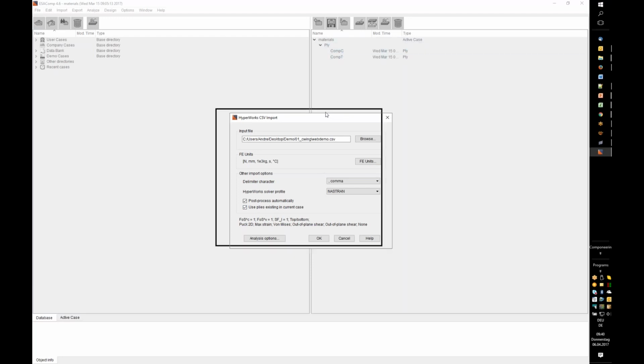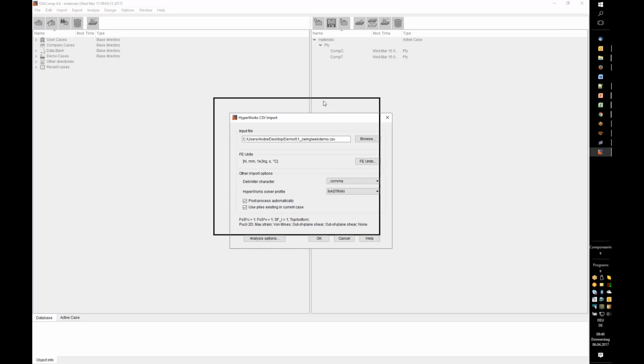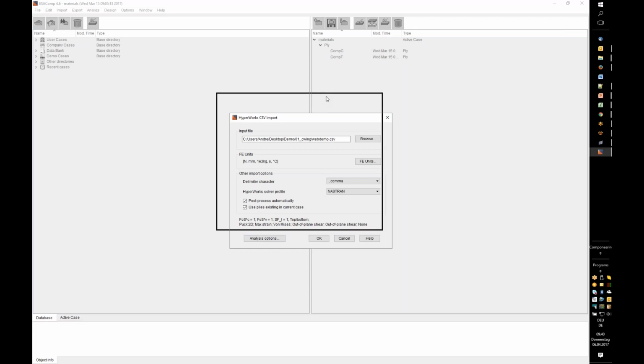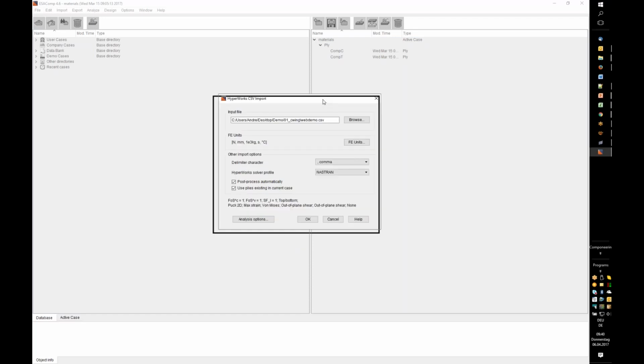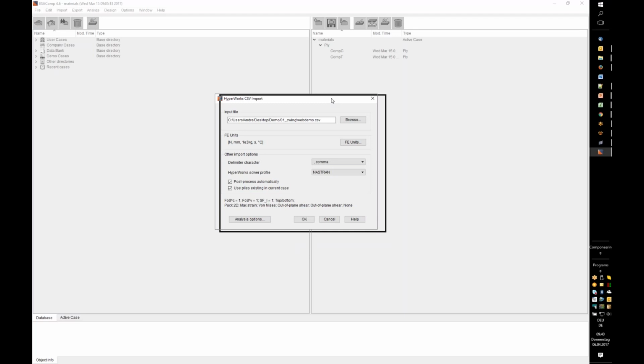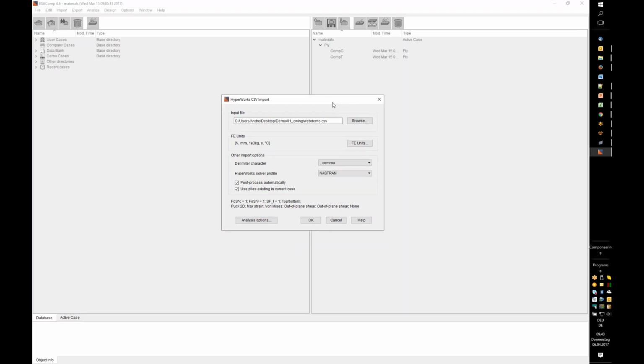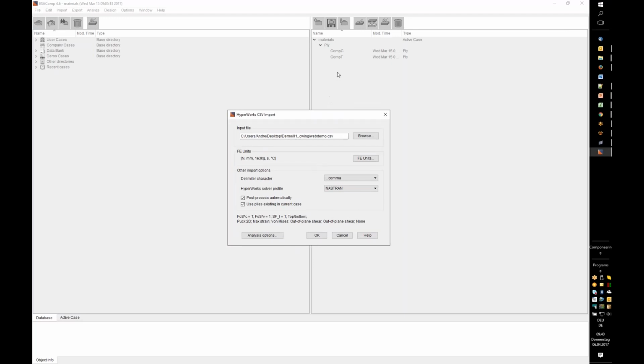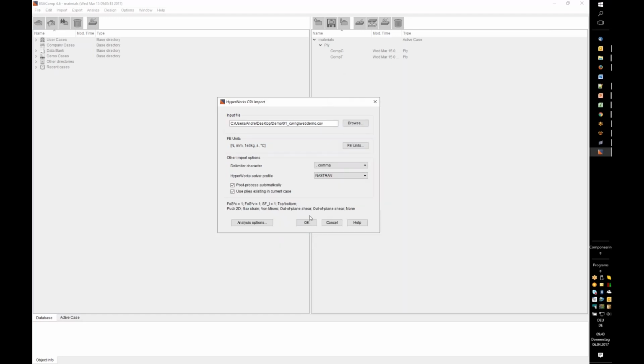We're going to add the same capability also for laminates, because ESAComp supports more capabilities in interlaminar shear handling than what the pcomp usually does. For ESAComp you can define the interlaminar shear strength depending on the interface, so which material interfaces with which, and not just as one value for one laminate. So you can get a bit deeper information on that side.